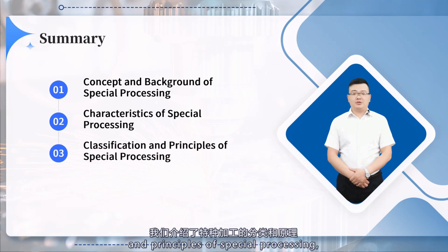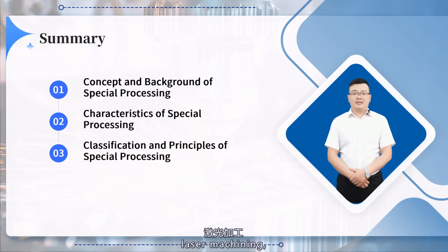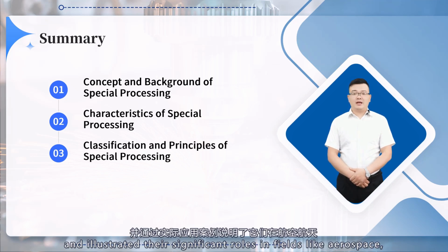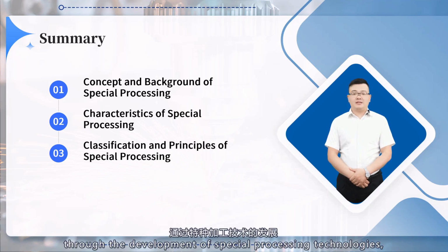Next, we introduced the classifications and principles of special processing, such as electrical discharge machining, EDM, laser machining, electrochemical machining, and ultrasonic machining, and illustrated their significant roles in fields like aerospace, electronics and information, and mold manufacturing through practical application cases.